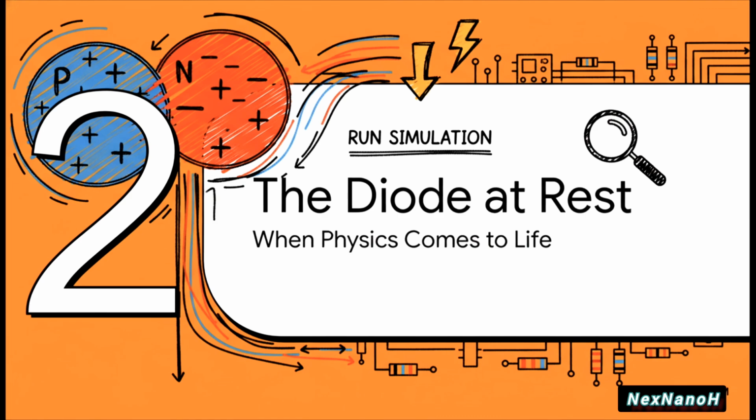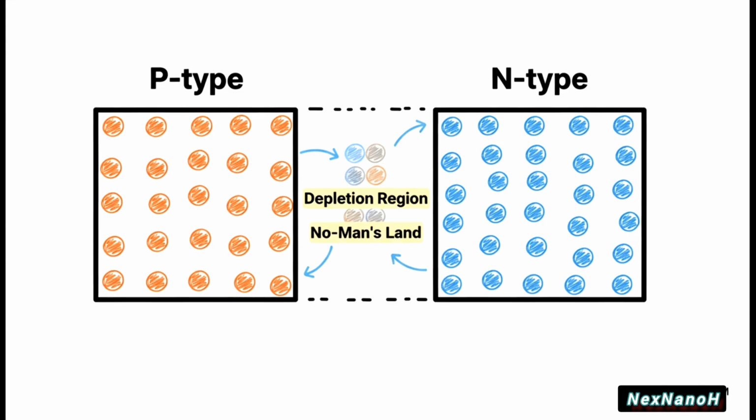It's time to run the simulation and watch the physics come to life. The second we start the simulation, physics just takes over. The extra electrons from that n side naturally rush over to fill the empty holes on the p side. This creates a really thin barrier right at the junction where all the free charges have basically canceled each other out. This barrier is called the depletion region. It's kind of like an electrical no man's land.